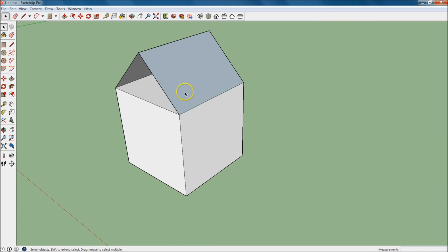What we're going to do is undo that real quick with Control Z, and do the push-pull tool right there. And as we're pulling back like this, you'll see that it goes blue, right? I want you to just hit Control. Did you see that? I just hit Control. Now on the Mac it'll be Command. If not, somebody comment and say it's not. But you're just going to pull it back and then drop it on that point right there.